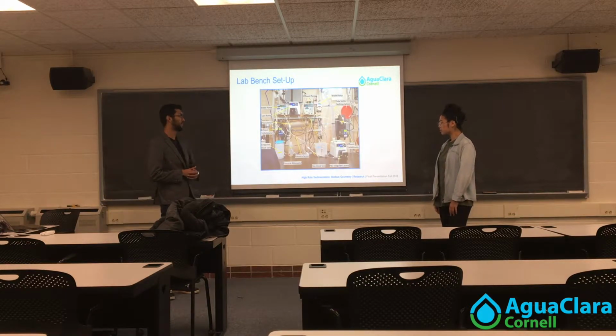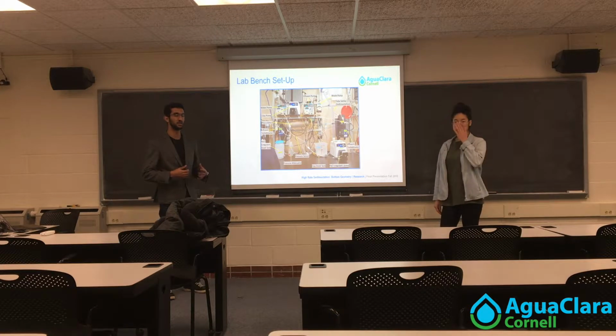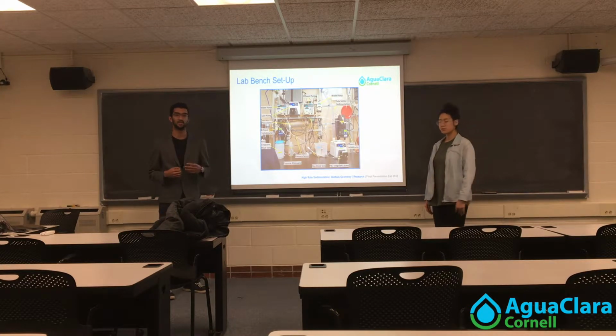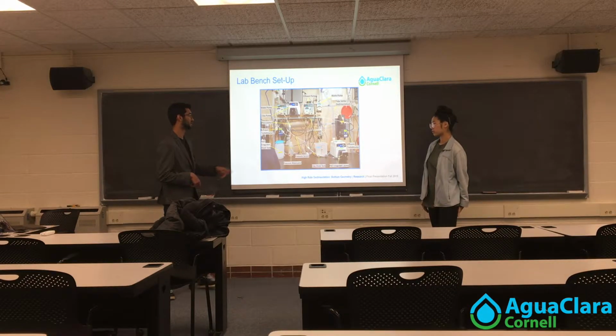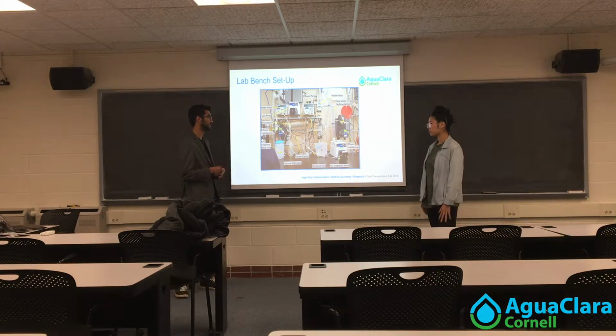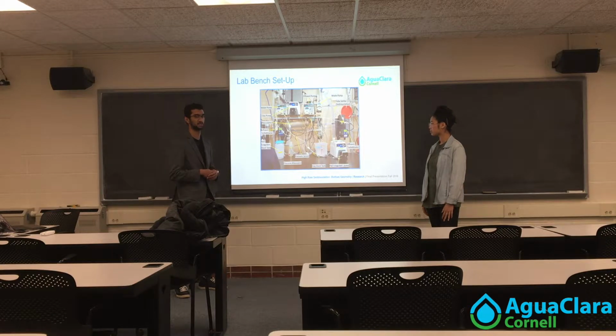This is the current lab apparatus that we're using to research. We're utilizing 3 water pumps, one to push water, one to dose coagulant, and one to dose clay. We're using a flocculator, which is coiled tubing that mimics the flocculator in the Omkara plant, and a sedimentation tank, which we will further discuss.